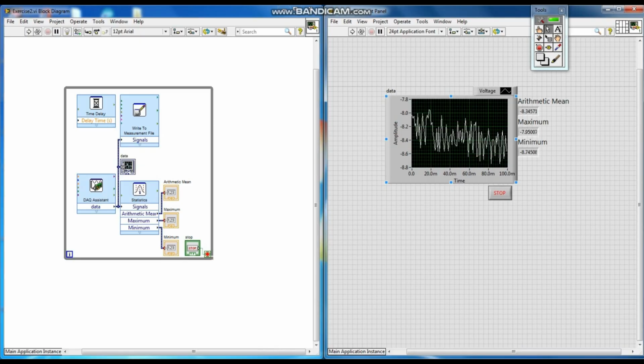Lastly, for exercise 5, our main objective is to use the Web Publishing Tool and LabVIEW web server to publish a LabVIEW VI as a web page. It's also focused on accessing the VI remotely using a web browser and requesting front panel access via the web browser.